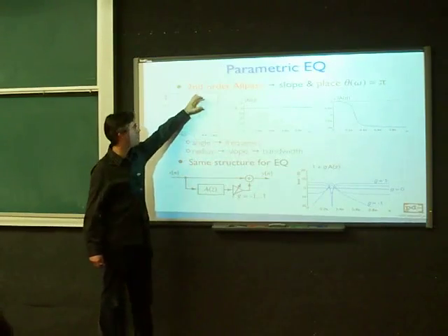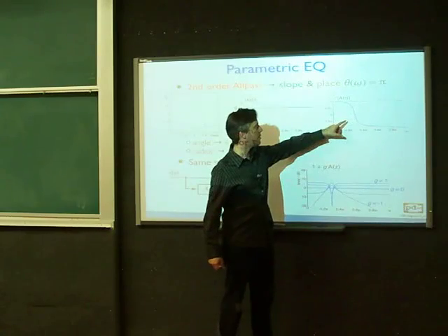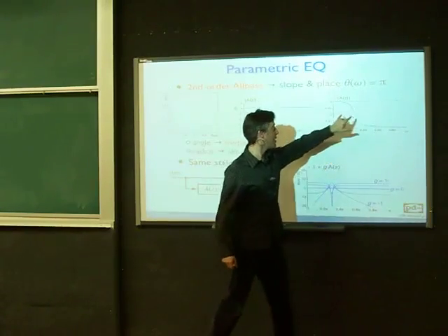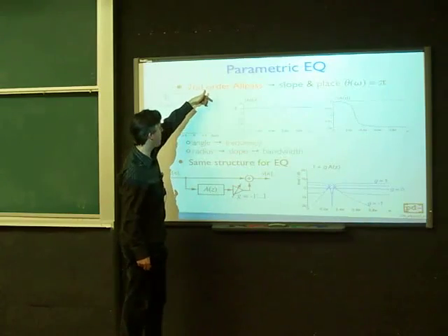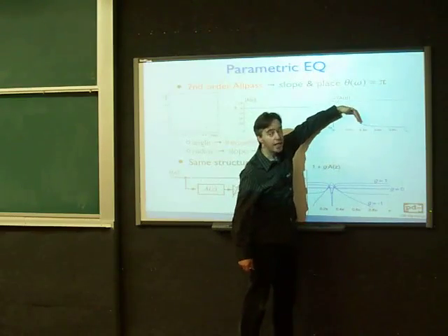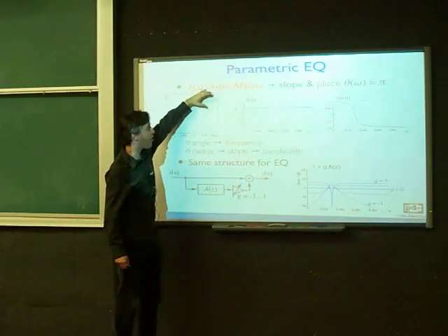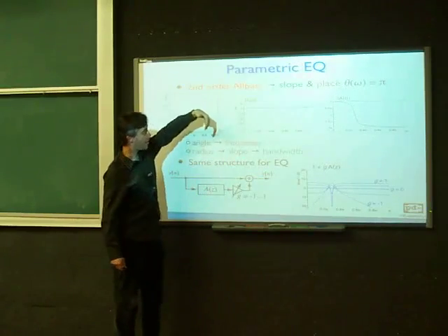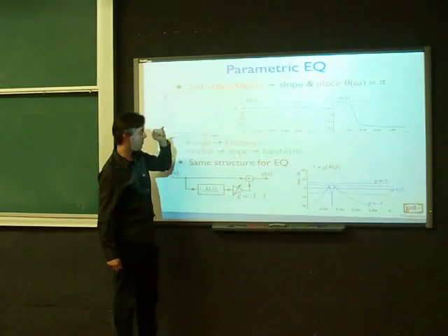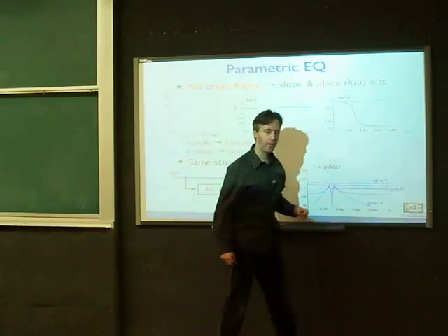And now what that means is that you can have this kink in the magnitude response, and you can move it around in the phase response. You can move it around in frequency by moving the position of this pole zero pair. And you can also change how sharp it is, how rapidly it changes, by changing the radius of this pole zero pair. The further they are, the shallower it becomes. The closer they are, the sharper it becomes. Because there are actually two poles and 2 zeros, the terminal phase difference here is 2 pi.